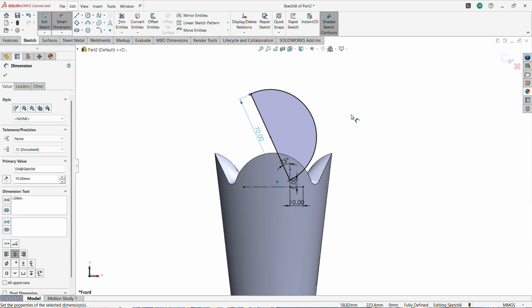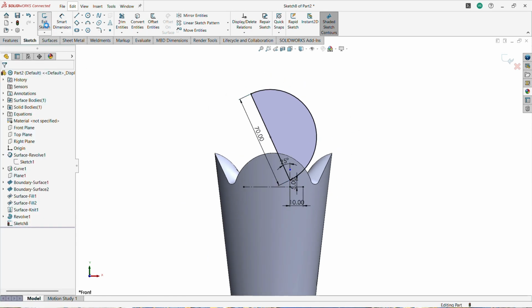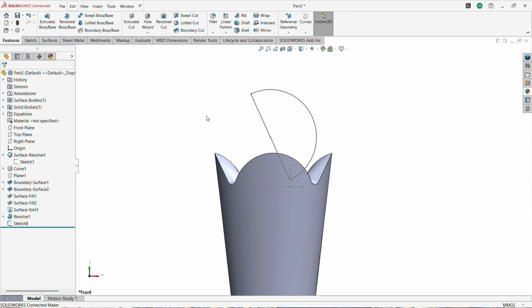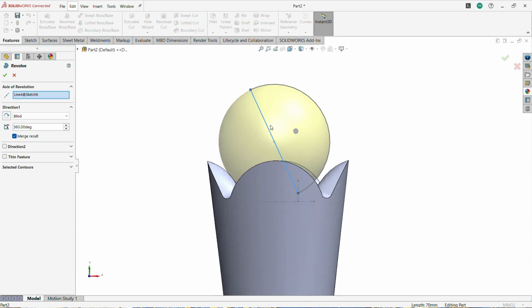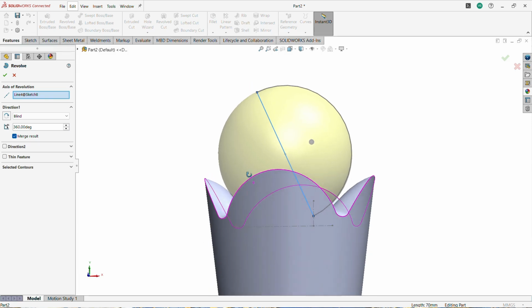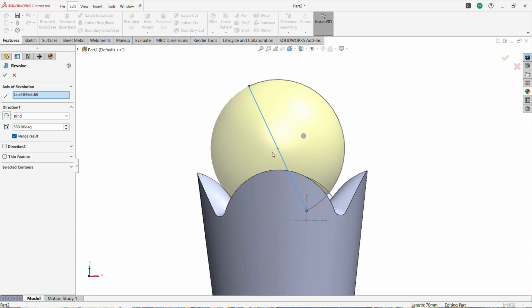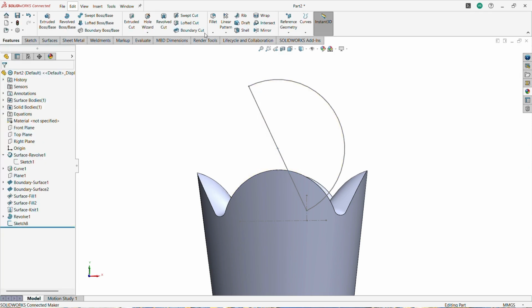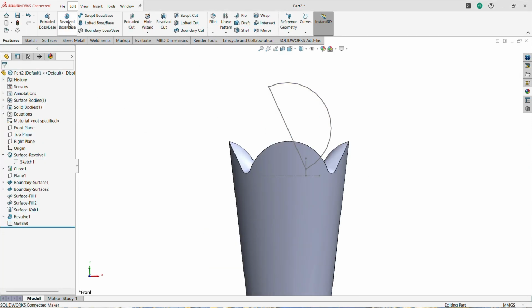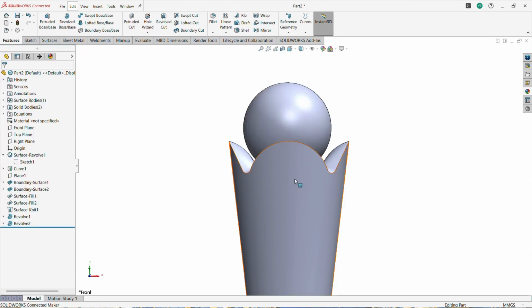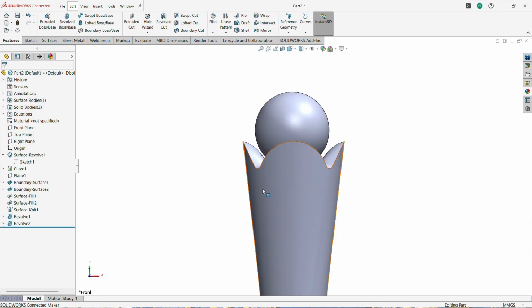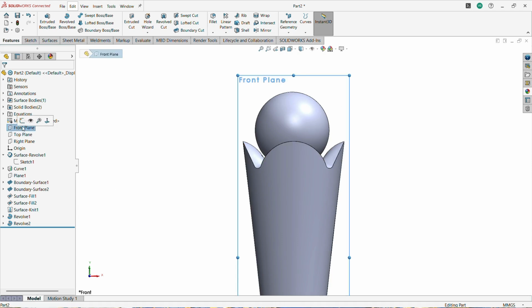We can use it to create a solid body under that. Once I draw a profile and fix this with overall dimensions, then create a revolved body by selecting this line profile. Use Revolved Boss to create a solid body. If you look at it, the dimensions exceed the values, also it is merged with the side faces itself. Now I am going to reduce the values to 60 mm and create a solid body again. The solid body is perfectly made with our standards.